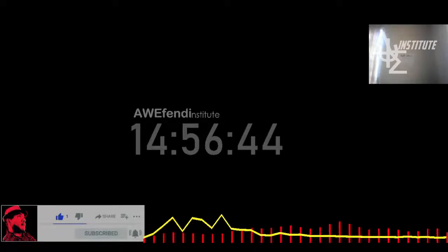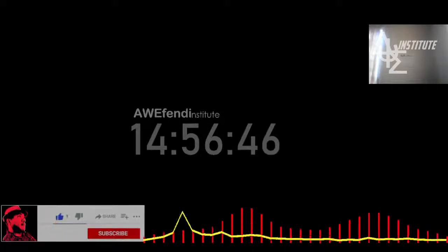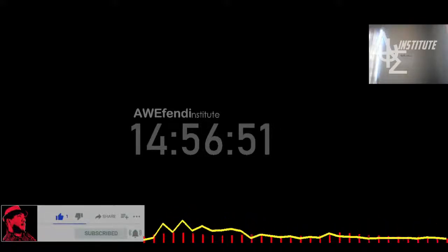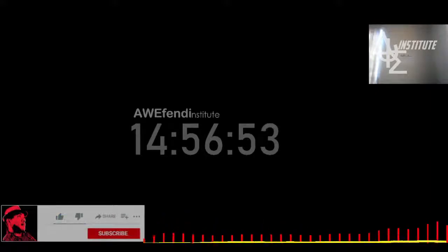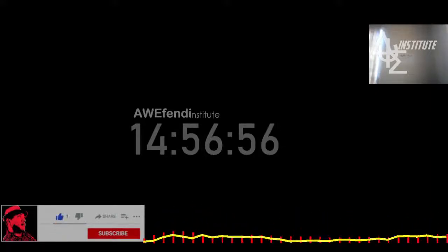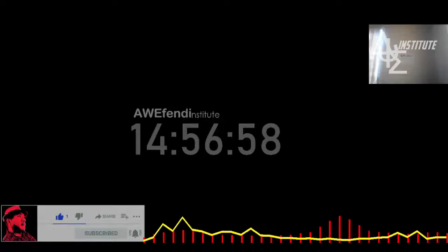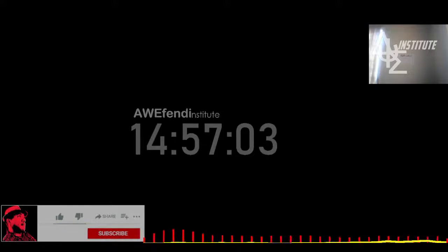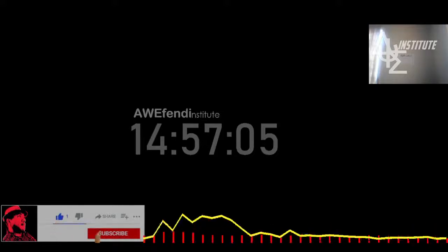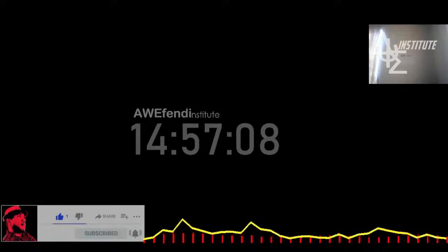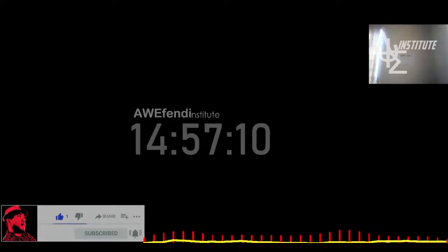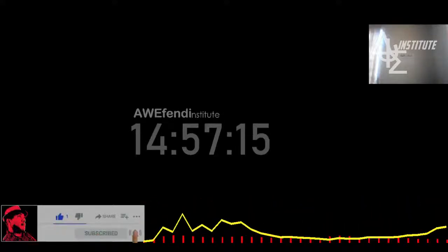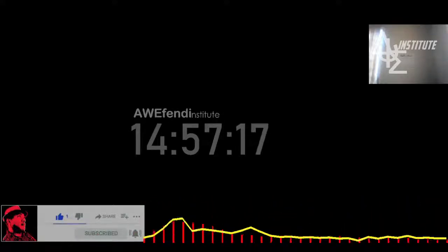And as I mentioned before, this value of 10 represents natural convection, but what we could do is move this to forced convection, which means air that is pushed through the heatsink. And this is more representative. This can be represented with a heat transfer coefficient of a value of 100 compared to 10. So if we change this value to 100 by representing forced convection, we can see how the temperature goes down from 200 back to 57, which is well within an acceptable range.